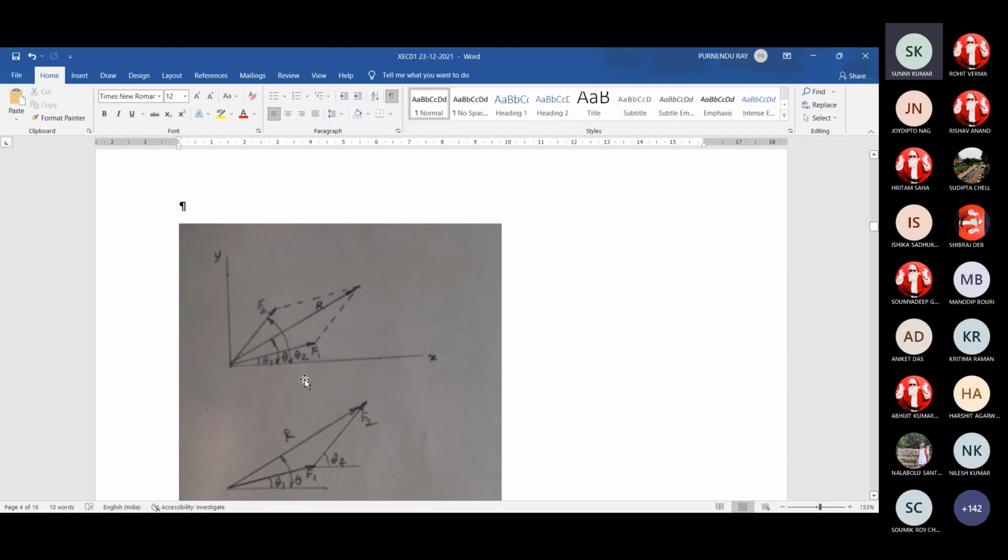If it is the direction n, so F1n, F2n and the resultant n or equilibrant n, all these components. For resultant, F1n plus F2n is equal to Rn. For equilibrium, F1n plus F2n plus the equilibrant n is equal to 0. So nothing to worry about horizontal and vertical directions. For any direction, you can find their components and make it 0.